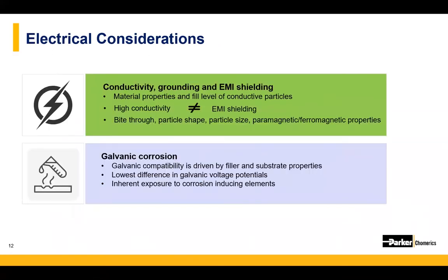As we mentioned, the electricals are the main reason for choosing the conductive compound over a non-conductive one. The electrical properties come from the conductive filler that is mixed into the binders, and it's an important step in your electrical considerations. Remember, we had discussed grounding versus shielding. It's the first question. If you look at something like silver or copper, they're very good conductors of electricity and inherently more electrically conductive than, say, nickel or graphite. Therefore, it makes them a better grounding option.